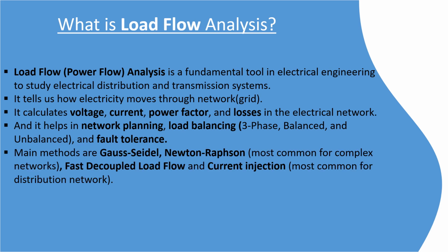In load flow analysis, the main methods are Gauss-Seidel, Newton-Raphson, most common for complex networks, fast decoupled load flow, and current injection, most common for distribution networks.